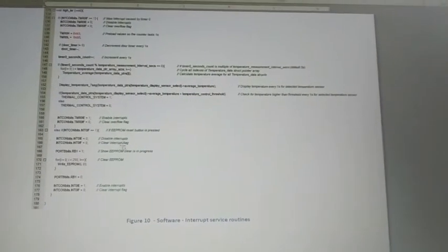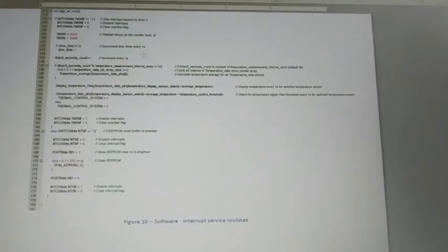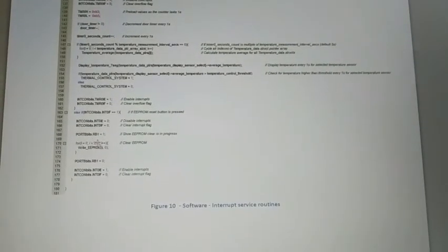And then here, this is the big if: instead of the timer 0 triggering the interrupt, if the hardware interrupt triggered it, then just clear the EEPROM here. It's a for loop that goes through each position of the EEPROM and writes 0 to it.